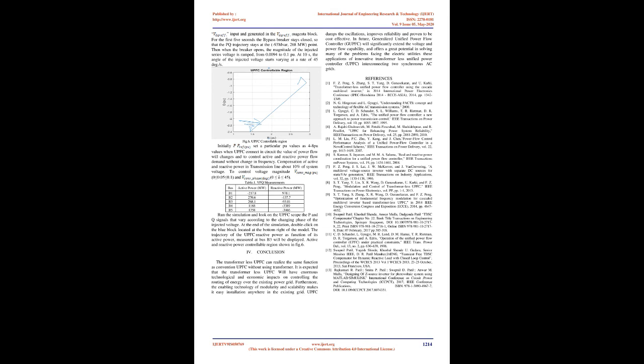BUPFC PQ controllable region. Now show control parameters, series converter. Select mode of operation equals manual voltage injection. In this control mode the voltage generated by the series inverter is controlled by two external signals, multiplexed at the input and generated in the magenta block.